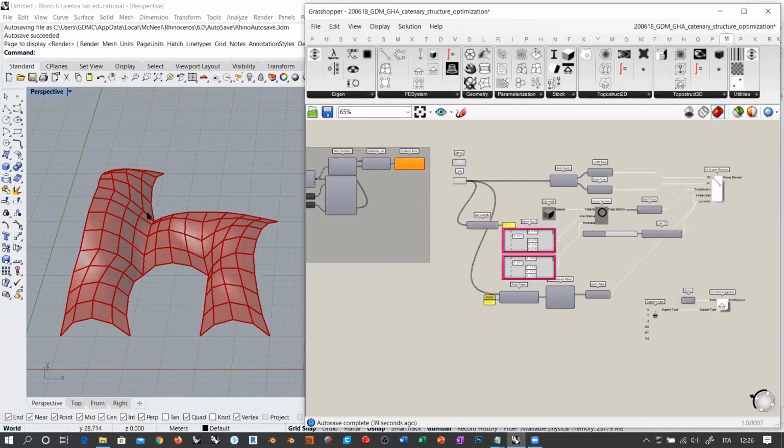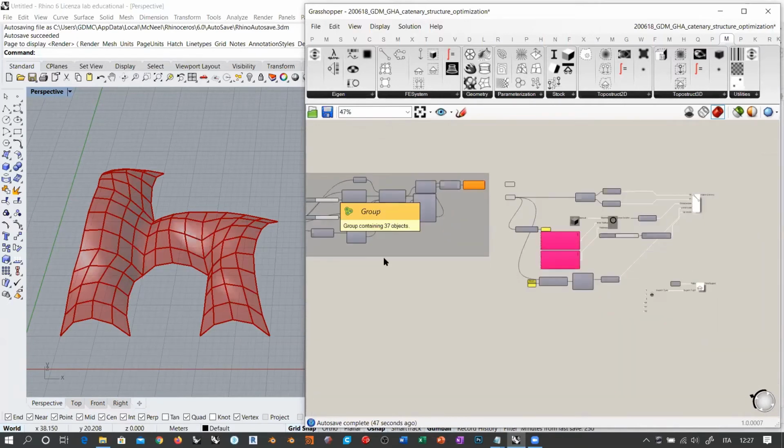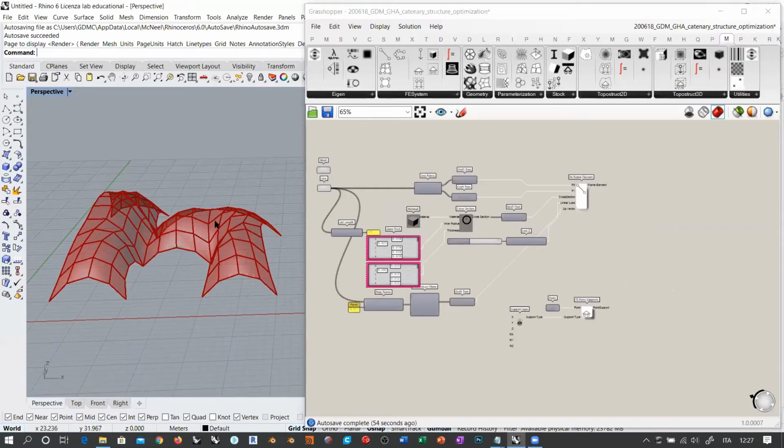If you apply an additional load to this structure in a specific point, you should do this starting from the Kangaroo simulation, okay? Because if you do this only in the structural analysis, only the corresponding element will react to that additional load.